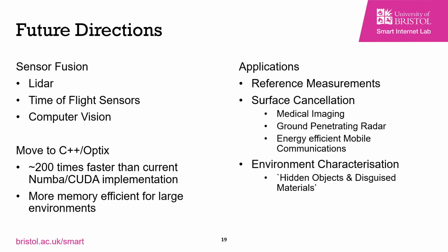And also, we talk about 5G and 6G, more efficient mobile communication. So when you need very dense cell towers in built-up locations, the idea of when you install that tower, doing a very quick site survey with a camera or a LiDAR, and then having that information in the cell tower itself, so it can become an intelligent node that knows where the major scatterers are in its environment, because it's able to run a very efficient propagation model and able to go, okay, well, I know that there are scatterers over here. And so in order to serve my customers that are about the cell here and also not interfere with my neighboring cells, I can steer in this fashion and really try and conserve energy while also offering the maximum data rate possible to the customer.